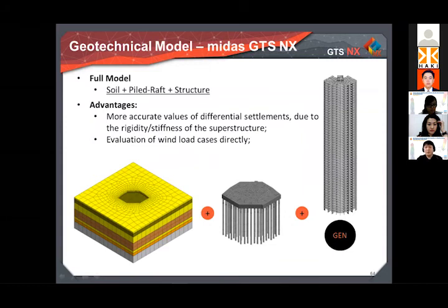Some numerical models of building foundations were made only by applying load or pressure at the base of the columns. It is like taking the reaction values for each column from the structural team and applying them directly to the model. This might neglect the distribution of loads in the superstructure and its stiffness or rigidity, as you wish. So those results differ from the real behavior of the structure, showing higher values of differential settlements.